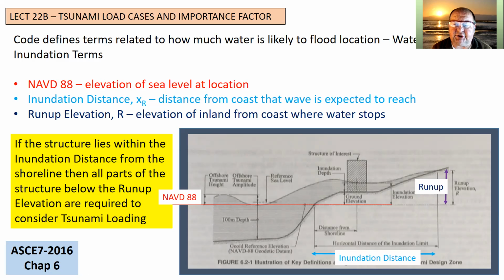And the elevation that it stops is known as the run up. If the structure lies within this inundation distance and parts of the structure are below the run-up elevation, we have to expect that the tsunami wave will impact it.